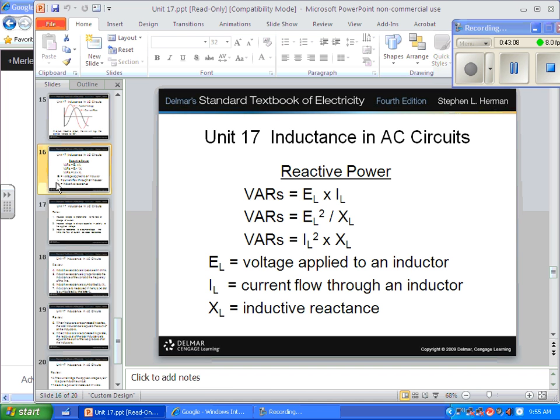Because once you build that magnetic field up, it's going to slow the current flow down, because you're going to be spending some energy creating that magnetic field and collapsing it, right? And so when you first start a motor, it's going to flow its pure DC resistance only, which is going to be anywhere from 4 to 8 times what your normal full load current would be. And that's why we have to change the size of the things when we look at motors. Okay? So once that field builds up, the current flow goes down because of the inductance. And now we're creating